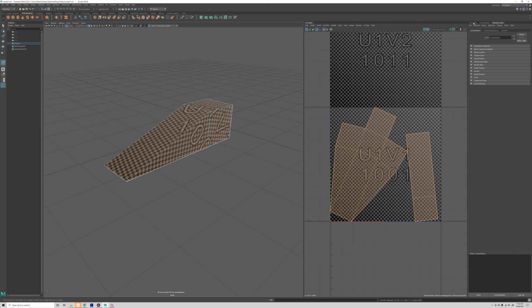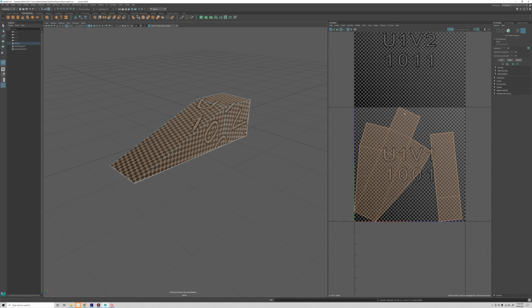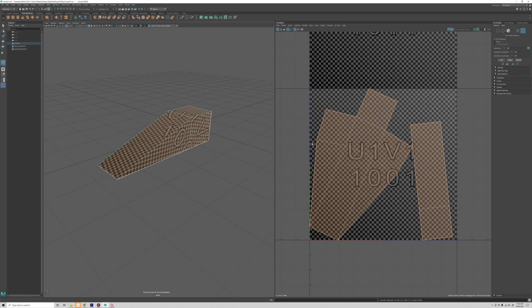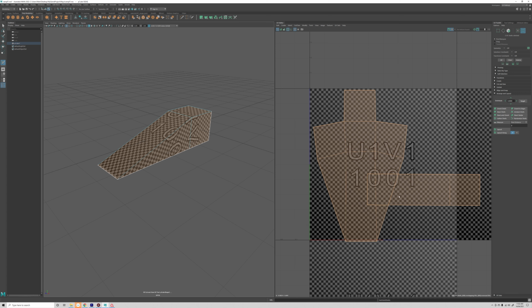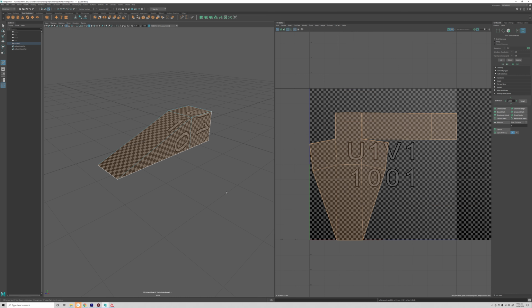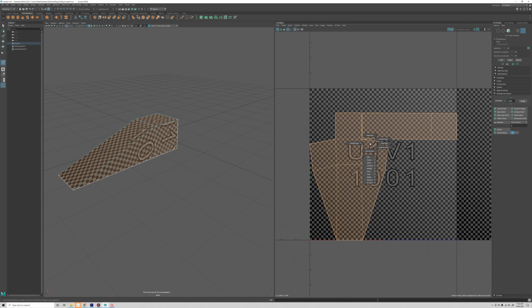In my UV toolkit, so these are the tools for working in this UV toolkit, I'm just going to open the last one, Arrange, and just click Orient Shells, so that just flattens them so that they're rotated flat. And now if I click Layout, it packs them into UV space. Now I'm just going to hit Q to get out of my 3D cut and sew, so that's the same as selecting the select tool.